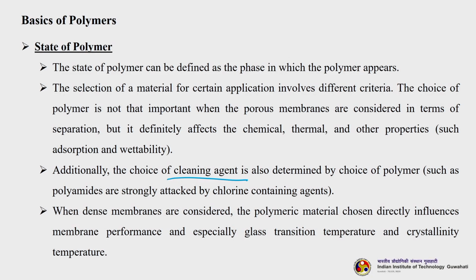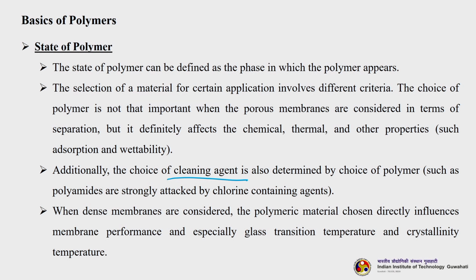So, the pores will get cleaned, but many times the pores do not get cleaned due to strong interaction of the solute molecules with the membrane material. So, you need to use some organic solvents, dilute acids, some alkalis or other solvents to clean it. This type of solvent may swell the membrane material. That is why the choice of polymer also governs the choice of cleaning agent. When dense membranes are considered, the polymeric material chosen directly influences the membrane performance, especially the glass transition temperature and crystallinity, when there are no pores, in non-porous membranes.